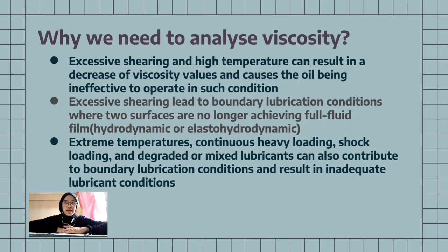Last, extreme temperatures, continuous heavy loading, shock loading, and degraded or mixed lubricant can also contribute to boundary lubrication conditions and result in inadequate lubricant condition.